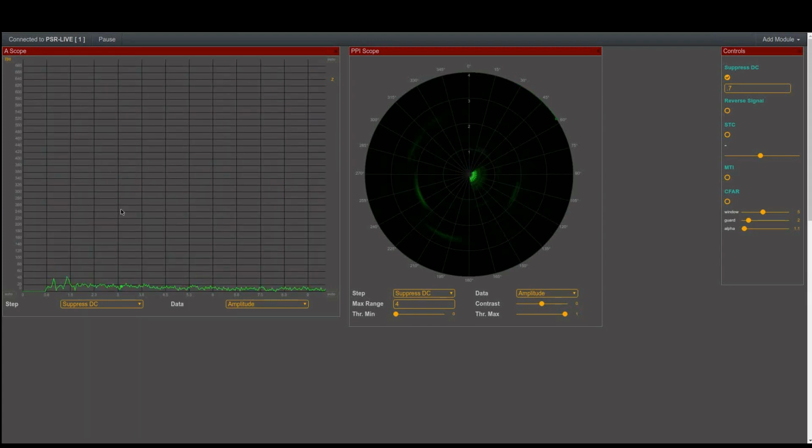When you compare PPI and A-scope, just be aware that the maximum range that we set in PPI is 4 meters. In the A-scope it's 10 meters. You see the source is almost removed. The cursor is now at about 6 o'clock in the PPI. So there at around 240 degrees, here you see our target. Strong in A-scope, not so strong in PPI-Scope. We will set that, but I think the system is also setting it because it's rearranging the maximum reflectors.